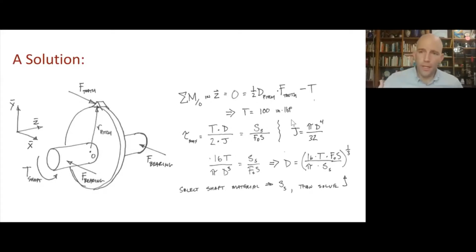Now, torque, we know, this torsion loading will result in a shear stress, and the maximum value of the shear stress, just like with bending, where we had sigma is My/I. For torsion, we have tau is Tr/J, or equivalently T times D/2, which is, the radius is 1/2 the diameter, over J. So this is our key equation to design this thing around torsion.